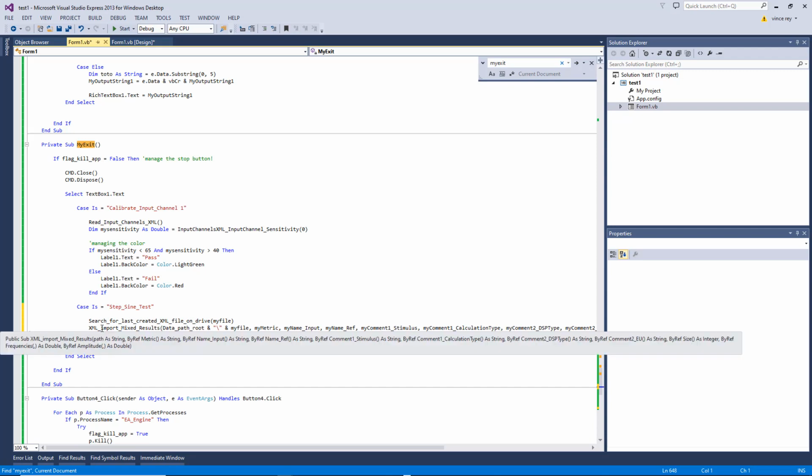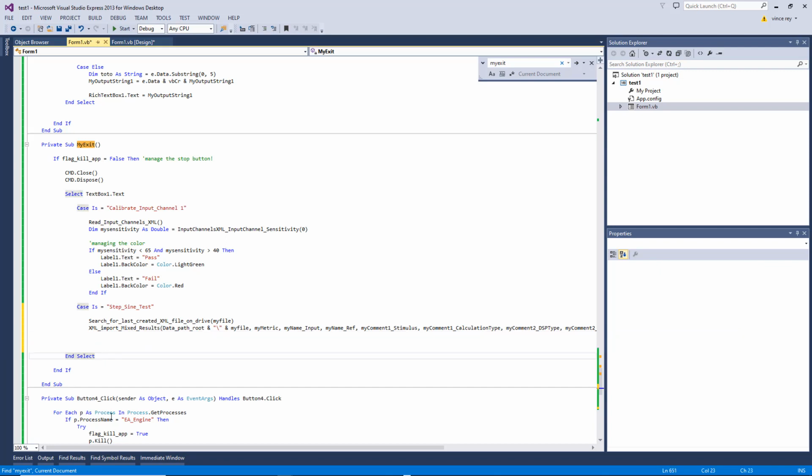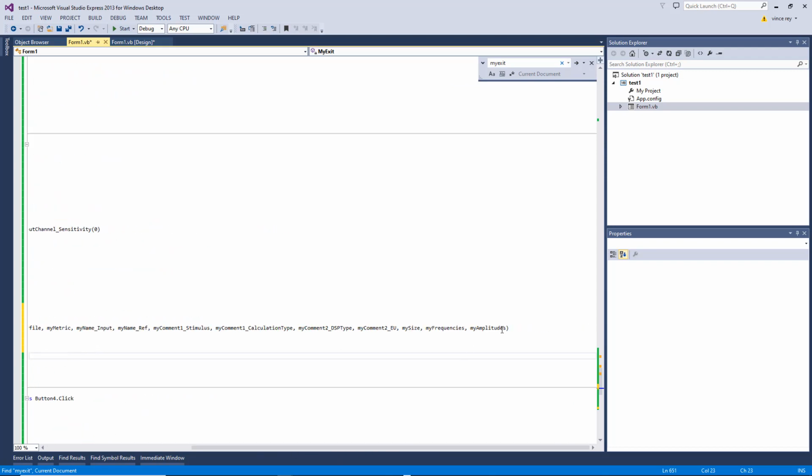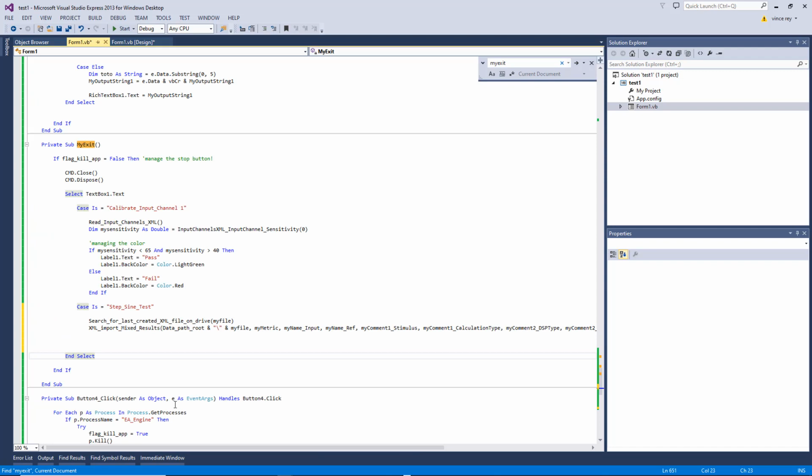So the XML that is generated by the engine here will contain the autopower spectrum, complex FRF, so real part, imaginary part, THD, and rub and buzz if you ask for rub and buzz. And so we'll have everything in one XML file, which will be very easy to read. So this is convenient because if your test is a given speaker, given headphone, all data will be grouped under one file only. Okay. All right, so that function will return a table called my amplitudes that will have all the amplitude data associated with the results, right?